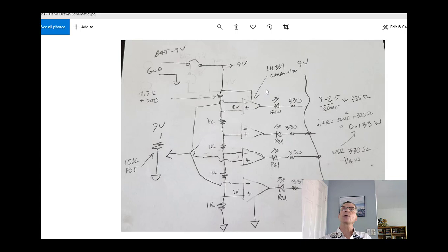So when we do our schematic, we're going to have to assign which pins go to this one, which pins go to that one, which pins go to this one, etc. And we're going to have to deal with that on our PC board too. It's called a multi-unit part. And you'll see the same sort of thing with op amps or AND gates or OR gates or NAND and NOR because they're more common. And I wanted to give you an example of actually doing this.